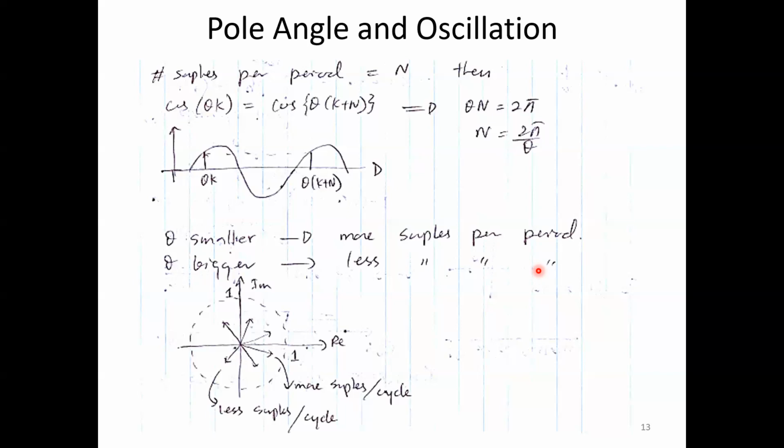How fast you get samples from a signal is very important. When you get more and more samples from the waveform, samples very close to each other, you are capturing the signal. You are reading the signal very accurately. So in that case, your angle is very small, right?